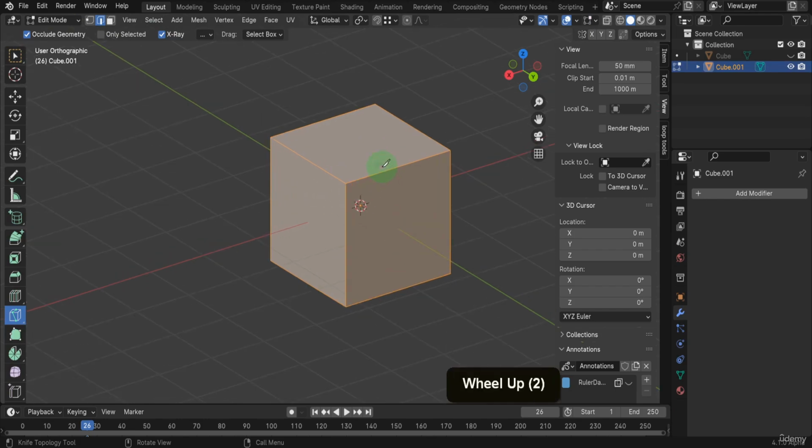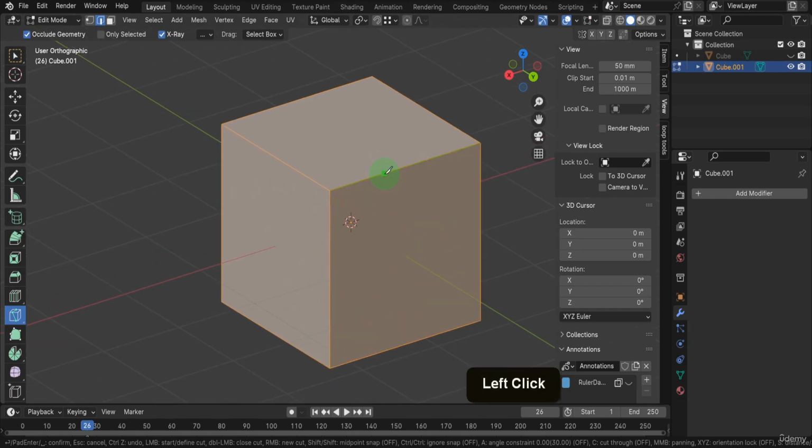To initiate a cut, left-click on an edge, which adds the first point of the cut. The edge that you are adding is now displayed, and on the bottom info bar, different options for the tool such as midpoint and angle become accessible. Hovering on the corner vertex or on an edge will cause the box to highlight, indicating where the next point will snap. Click on the edge, then hover on a corner vertex and click there. To complete the cut, press Enter.